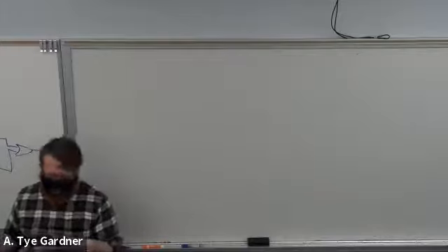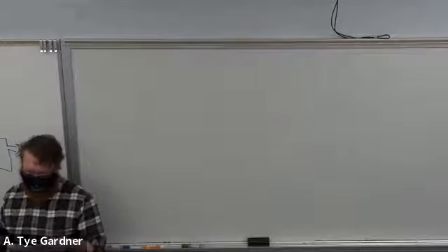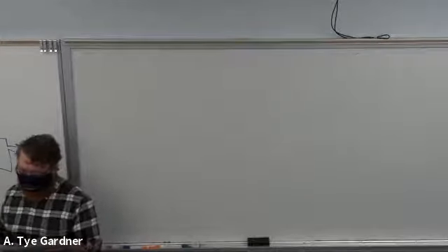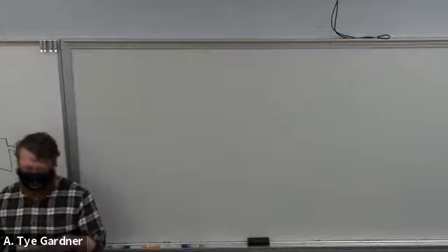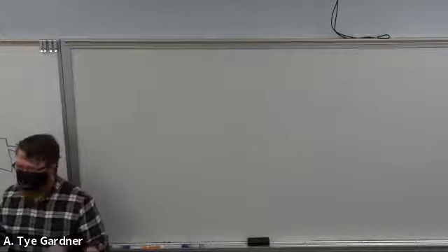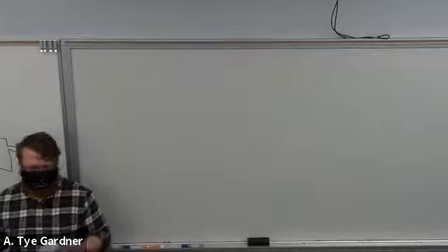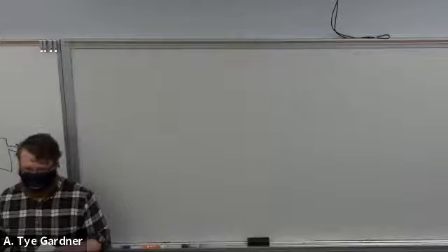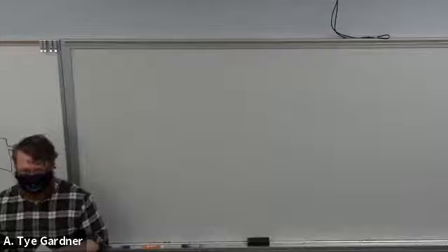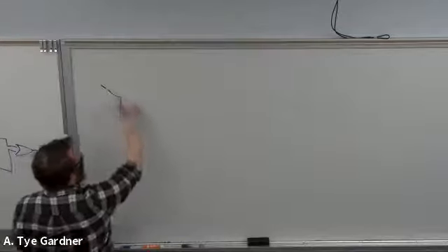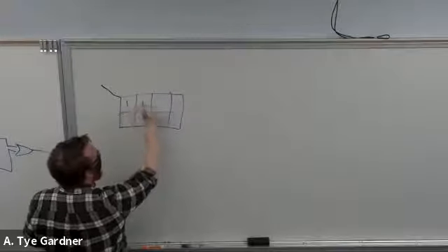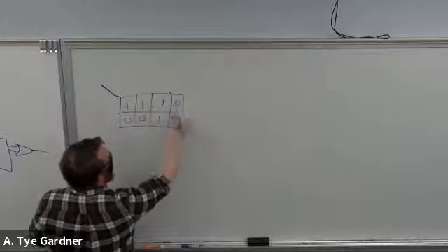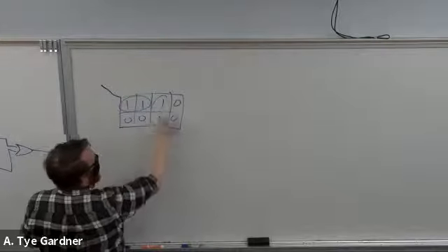Part A asks, what is an indicator that there is likely a static hazard that you can see just by looking at the K-map with the implicants circled? So how does a K-map warn us that there's likely a static hazard? Yes, adjacent ones that don't share an implicant.